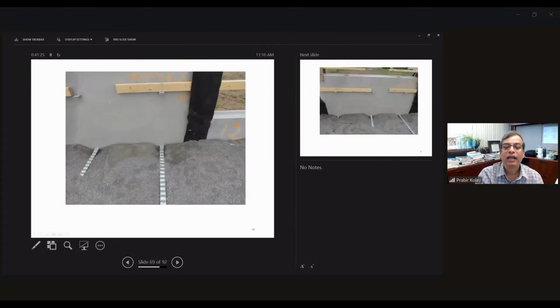So you can see here, this is the reinforcement strip, and this is the gravel type of material they used, and this is the horizontal spacing from here to here, and this is the next one. After this, they will fill it with the granular soil, and then the next one will be attached on this groove over here. So this will come horizontally. That will be the vertical spacing, and this one you can see the horizontal spacing. This is how they do it with this MSE wall.